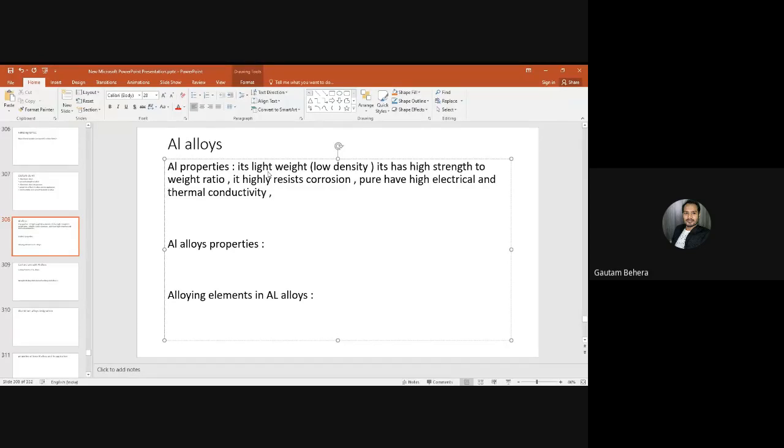It is cheaper, obviously, and the core is made of steel, but the outer part is made of aluminum, right? And you know why the core is made of steel? Because these aluminum wires are very long and do not have much strength. I'm talking about pure aluminum. So the strength is provided by the steel, but the electrical conductivity is provided by the aluminum, right? Because they are long wires, bending may take place. So strength is required, and that is provided by the steel.